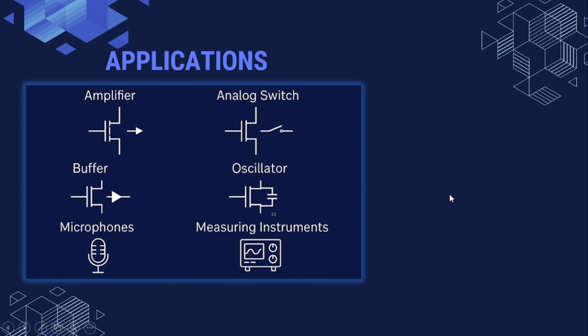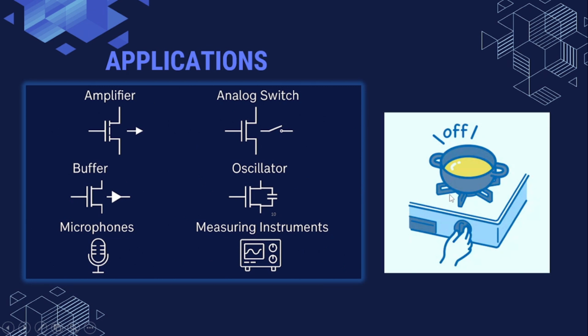An effective way to explain the working of a field effect transistor is using the analogy of a gas stove with regulator control. Imagine a gas stove burner that you want to turn on or off and control the flame intensity with a gas regulator knob. The regulator knob is used to control the gas flow from the cylinder to the burner. Likewise, here the gate voltage controls the current flow from source to drain, turning the device on or off and adjusting the flow level.